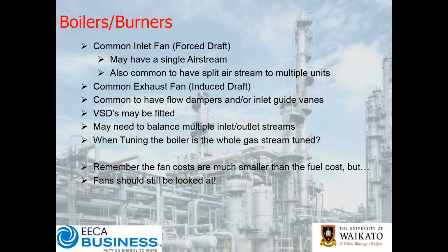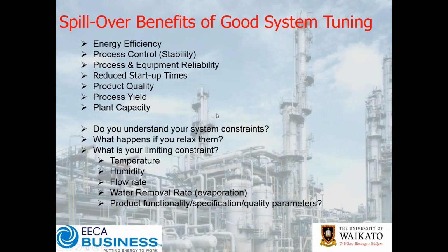So remember that the fan costs on these systems are going to be much, much smaller than your fuel cost, but it means that the fans should still be looked at, because those fans are going to have a massive impact potentially on the efficiency and performance of your system, even though they might not be considered the primary cost center if you're worrying about your boiler. It's very easy to ignore, and they're often the root cause of many of your problems.